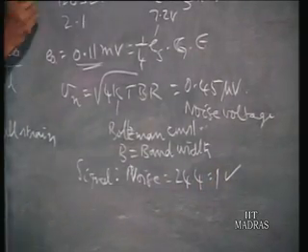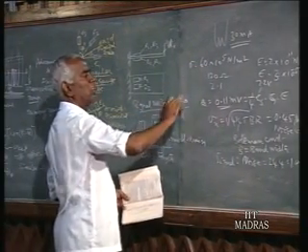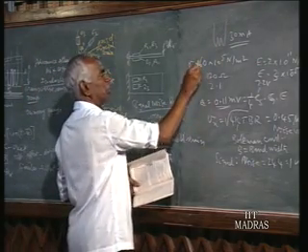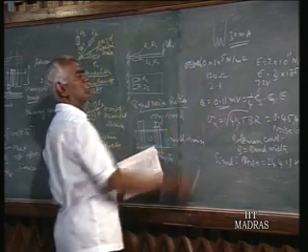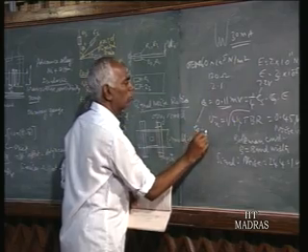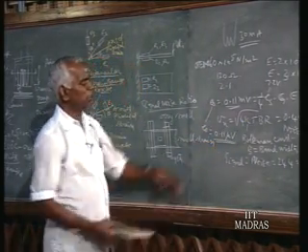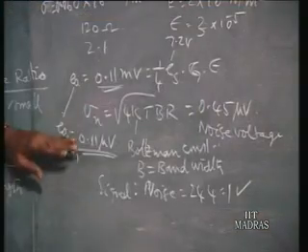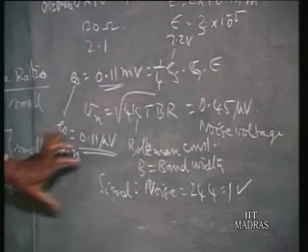That is the case when we have weakened it, so you will have sufficient stress. Suppose we paste the strain gauge on the existing rod, and the stress is only this much: stress is equal to 0.060 into 10 to the power of 5 Newton per meter squared. Then you will have EO equal to 0.11 microvolt. In this case we find the noise is larger. Noise is 0.45, 4 times larger. So we find the signal is lost in this case.